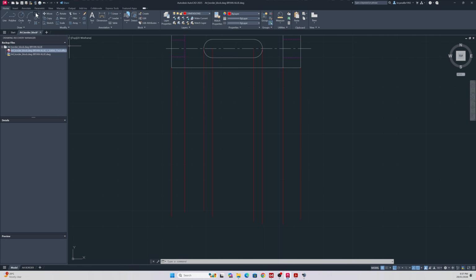So what I'll do now is go into the rectangle. I'll change the layer to the outline, and go to rectangle. Because it was set from the end, the distance should automatically be given, but I need a thickness, and the thickness should be 9 mil.